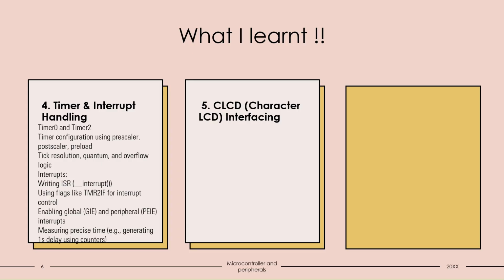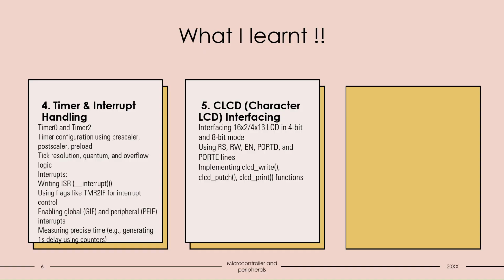In CLCD, LCD interfacing of 16x4, we used, by mistake I have written here 16x2. We used a 16x4 LCD in 4-bit and 8-bit mode using the RS, RW, EN, PORTD and PORTE lines. We used these RS, RW, EN in the macros of the header file, implementing the CLCD write function, CLCD push function and CLCD print function. Cursor control and printing strings and characters using macros like LINE1(x), LINE2(x) to manage text positioning.